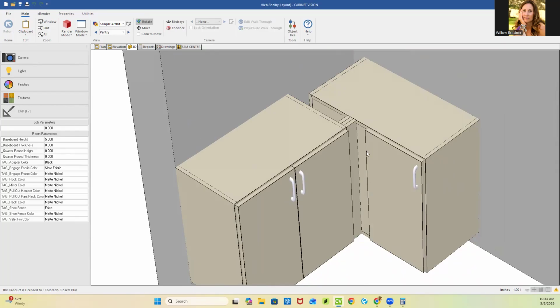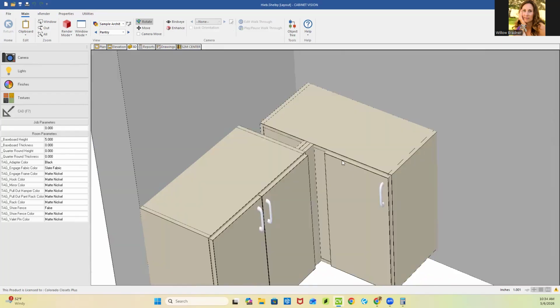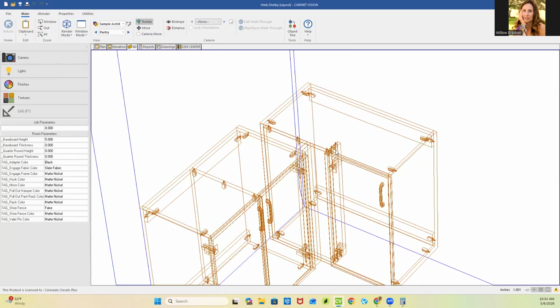If we were doing drawers, there'd be more crazy things that need to happen, because this cabinet would need a panel here to catch the guide, but we're still trying to leave it open here. So we probably have a thick shelf going all the way across, boxing out the top, and then we create a full length partition back here to catch the guide, and then the drawer would slide in the top. Under that, we would have this narrow strip catching the hinge and all of that jazz. More complicated. Yeah, I hear you.